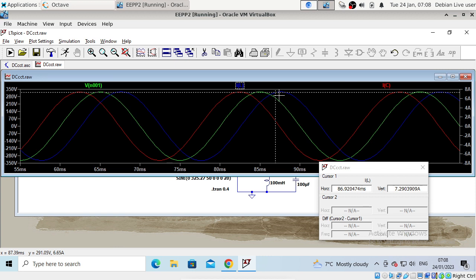Conversely, for the inductor, in order to change the current in an inductor, you have to do work. So you have to apply some voltage to the inductor to change the current. So as a result, the voltage has to be present first in order for the current to change. So therefore, maybe it's not surprising that the current in the inductor is lagging behind the voltage that's being applied to it. So that's why the capacitor current is going to be leading and the inductor current is going to be lagging, or in other words, happening later.